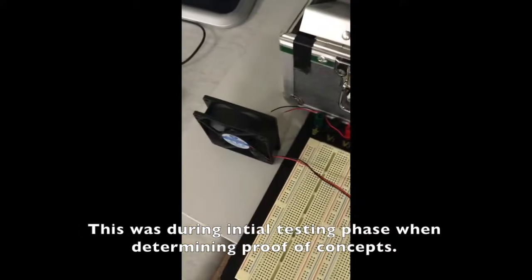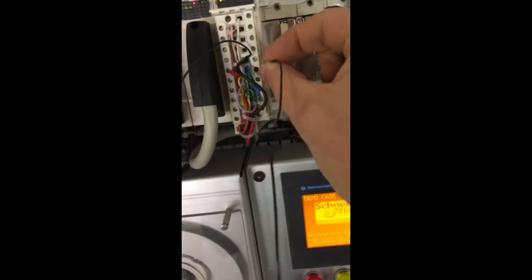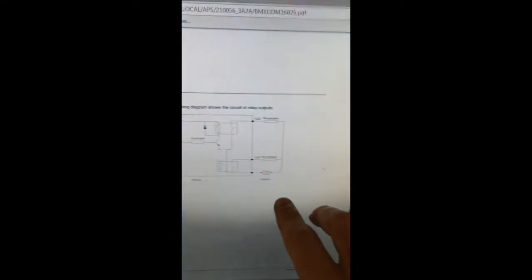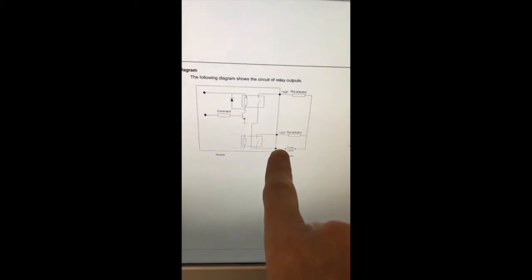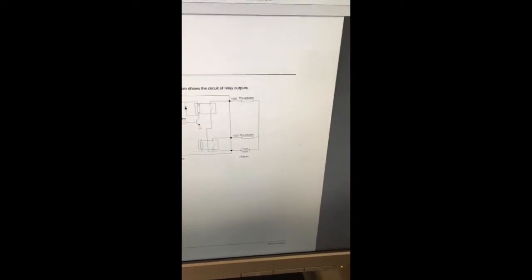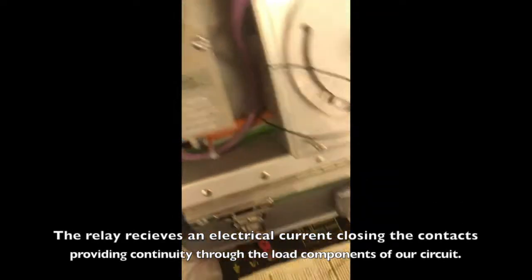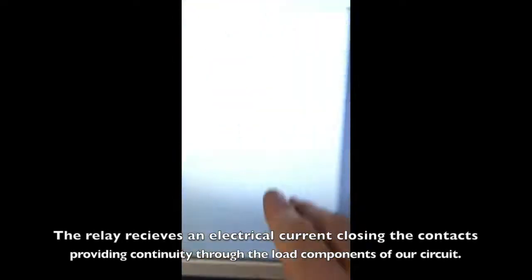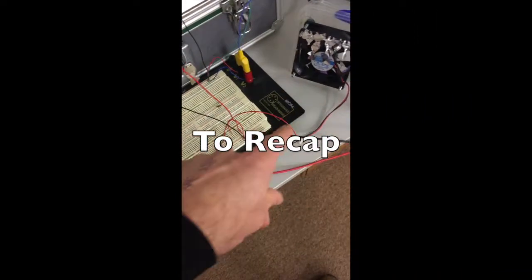Here is that circuit in real life with our positive input coming from the relay module, which on our circuit diagram is this node here. This is our power supply, as seen internally on the relay module. That will be supplying 24 volts to this side, and there is our internal relay. We needed to place a 100 ohm resistor in series with the DC fan for 12 volts to be seen across it.